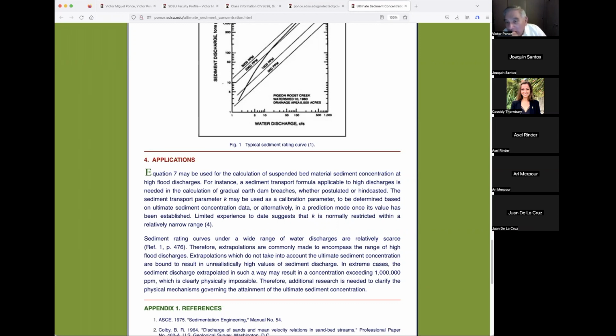Italy, northern Italy, 1960, 1961, they built this huge arch dam. Now, we don't build any more arch dams, and the reason is because there are no sites that would take an arch dam. The arch dam is not like a gravity dam. The gravity dam is going to sustain itself on its own, by gravity. The arch dam doesn't have any gravity, so it has to be against abutments that are very strong, like a hill, two hills, abutments that will hold the dam in place so that it doesn't go anywhere.